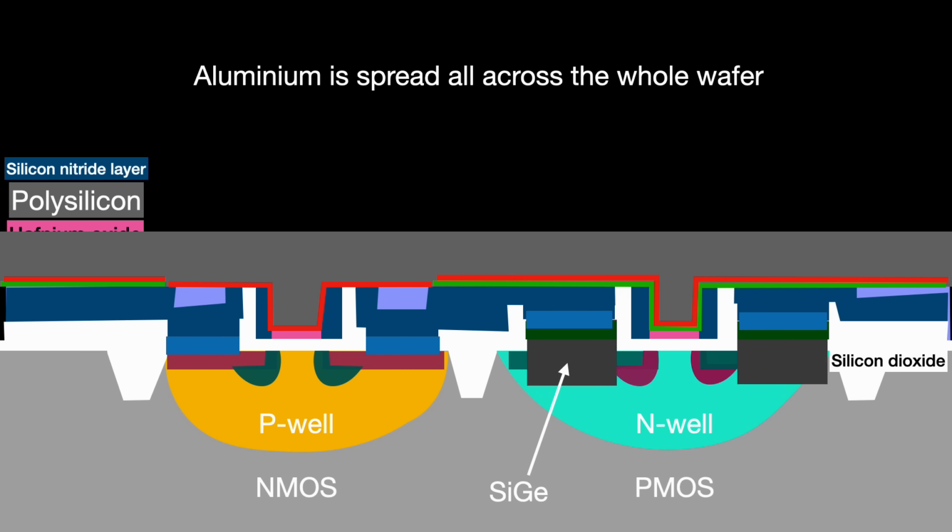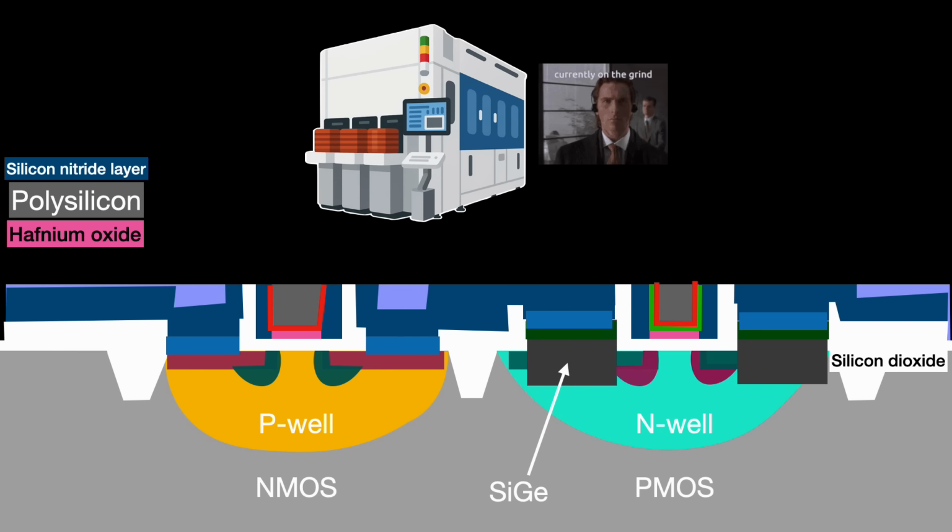Intel used simple aluminium to make the gate, applied presumably with some form of CVD. I have also seen tungsten used in some node variants. There is excess aluminium after this, so CMP is used to polish down the unwanted aluminium and complete the metal gate. The gate is done.